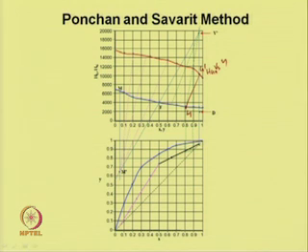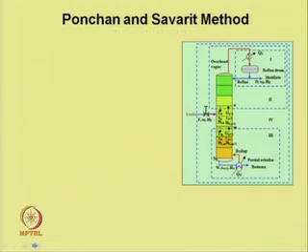Now, we have to locate the feed plate location. To draw the feed line, we need to do the material and energy balance equations over the feed plate.